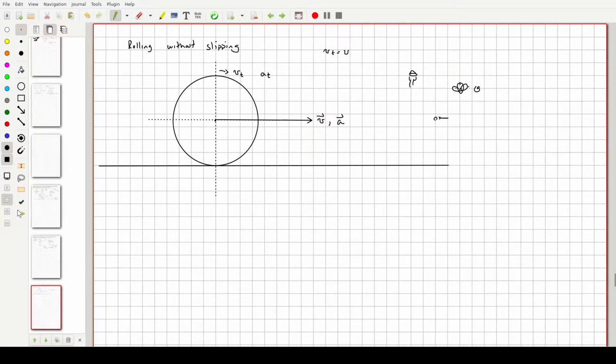And that rotation through the crankshaft is usually attached to a transmission. In a rear-wheel drive car, the transmission has got a bunch of gears in it, and what they do is, through rotation, either make one rotation of the engine be more than one rotation of what goes out of the transmission, or less. That would be the difference between first, second, third, and fourth gear, and whatever else your car does. Well, all this is attached at the end of the transmission to what's called a drive shaft.